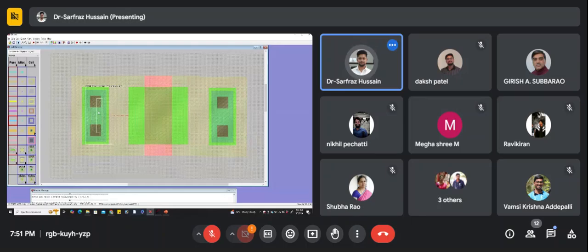Now, when you bring it together, see here, if you bring this one and it is less than 3, it will show an error. So you have to keep it at least 3, and then right click here, and you can connect this one with the PMOS like this. Same thing goes for the other side. First you align this one properly. Once you have aligned this one, bring it as near as possible. If it is too near, then you have to make it somewhat here. Then right click and connect it. So this is how you can connect these two together.